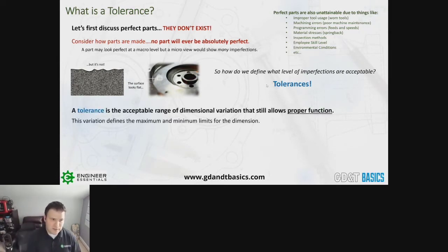And really, a tolerance is the acceptable range of dimensional variation that still allows for proper function. If design wasn't hard enough, making sure that the thing doesn't explode or break when you put stresses on it, you also have to make sure that if they screw it up, you know how far they can screw it up before it still properly functions, right? You need to allow that amount of variation. So this variation defines the maximum and minimum limits for any dimension, whether it be geometric, size, it could be spring force, right? You have a tolerance on that.